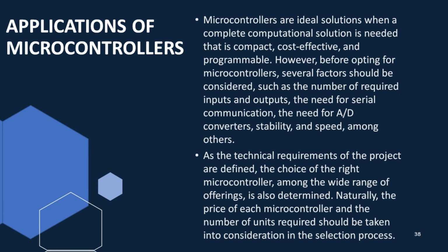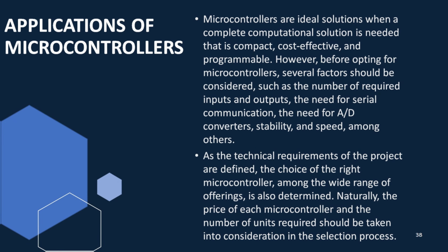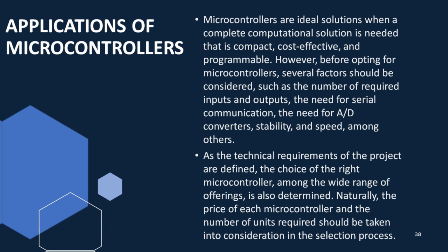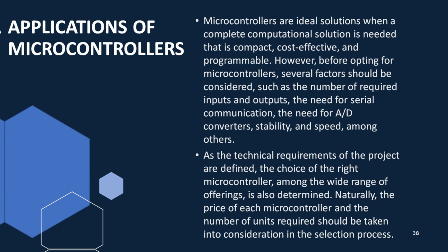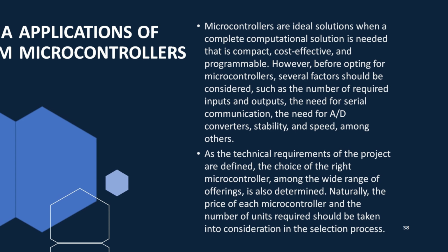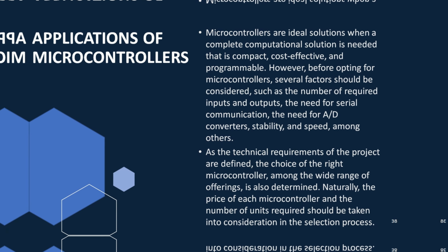However, selecting the appropriate microcontroller entails careful consideration of factors such as input and output requirements, serial communication needs, the necessity for A/D converters, stability, and processing speed, among others. Once project specifications are delineated, the choice of the suitable microcontroller from the diverse range of offerings becomes paramount. Factors such as the price per unit and the required quantity of units also influence the selection process.